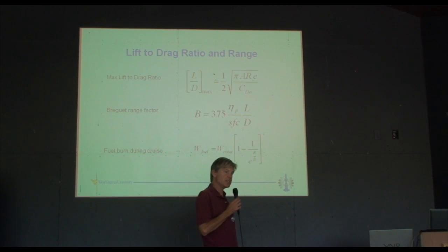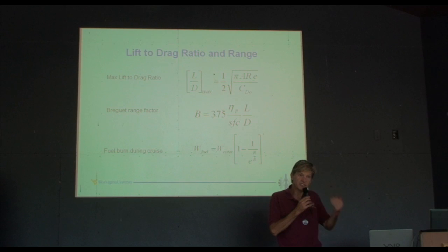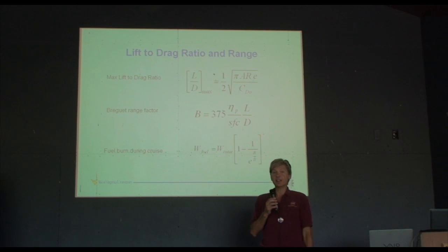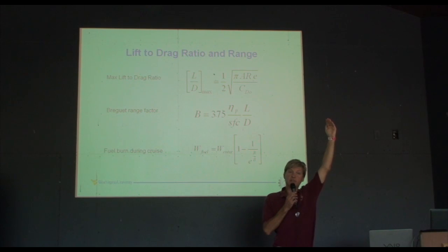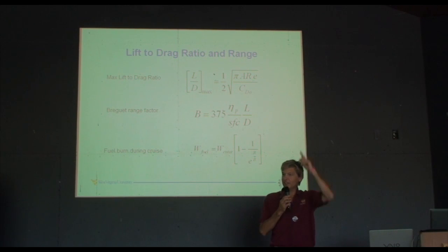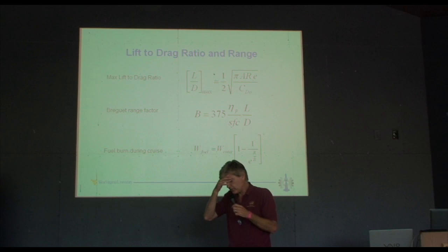And by reducing the density, you change the angle of attack. So you can drive the wing up to the angle of attack where you're now at an L over D max of 17.4. Bingo, that's why everybody's up there. So anyway, back to what we were talking about.